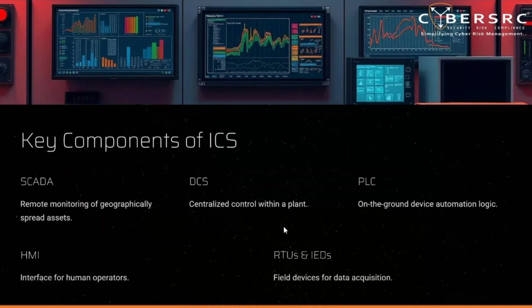A distributed control system is used for continuous monitoring of complex processes. They decentralize functions over multiple controllers and field devices, but provide centralized visualization and management. DCS also includes advanced process controls and sequence management to ensure fault tolerance.